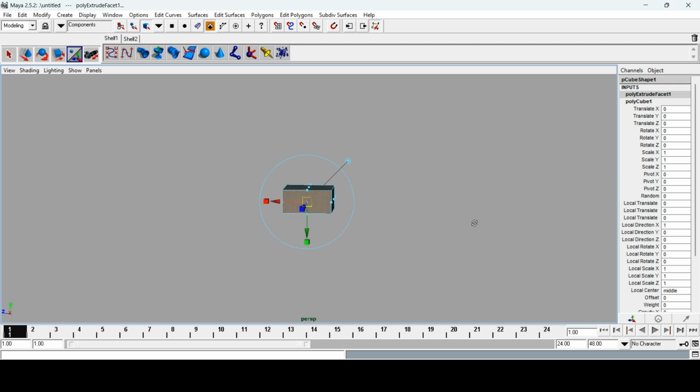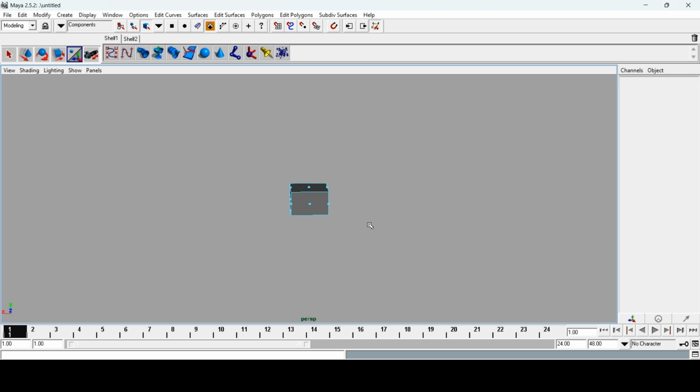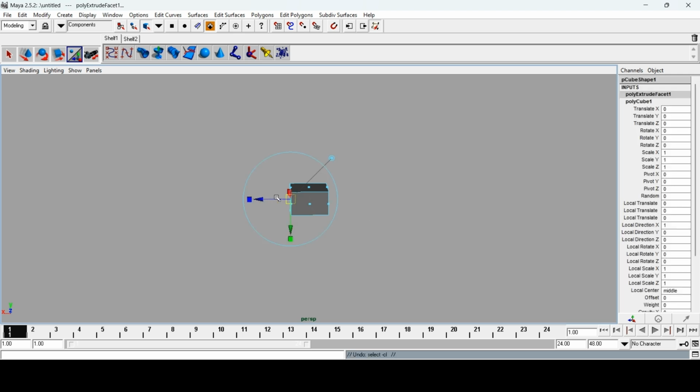See, when we click on extrude there will be an arrow and a box. Let us see what the uses of it are also. Now just click on this arrow and drag it outside. Now we can observe that the boxes are extending, meaning extruding. If we look at it, the boxes are extruded at both faces. Because we have selected two faces, it expands parallelly on both sides.